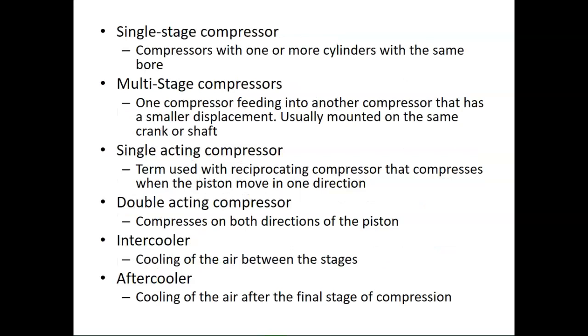So you have single stage compressors, where you have one or more cylinders with the same bore. Multi-stage compressors are very, very common. This is where one compressor feeds into another compressor that has a smaller displacement. You have a single acting compressor, which compresses when the piston moves in one direction, and a double acting compressor, which compresses when it moves in both directions.